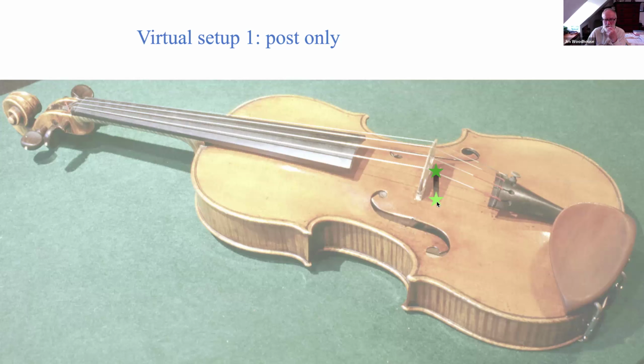In order to fit the post, this is the point where I'm going to take advantage of that discovery from earlier that the torsion springs really don't matter. I only need to think about the axial effect of the soundpost. I know the post details. I know what it's made of. I know its dimensions and its weight. So I've got a perfectly good model of that. But I really can't guess what these contact spring stiffnesses are.